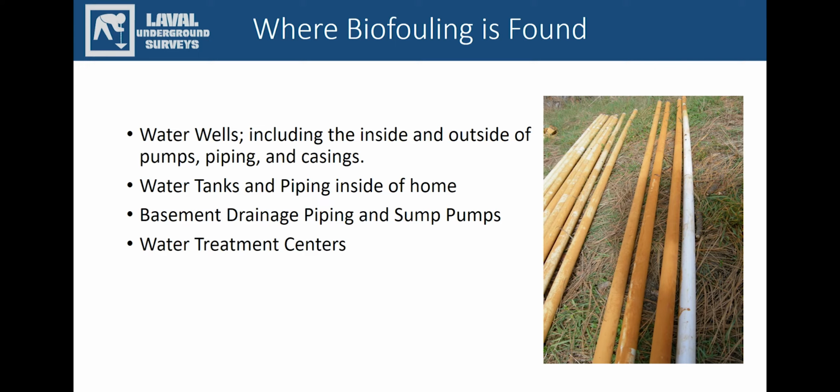Most recently, we've seen an uptick in the basement waterproofing industry looking for answers to iron bacteria problems. Because basements have water that flows into the drainage and sump pumps, the piping and the sump become clogged with iron bacteria. It's widely misunderstood in the basement waterproofing industry, and often people spend thousands upon thousands of dollars to remove the piping and the sump just to relieve the clogging. I consistently talk to homeowners who change their sump pump every single year because they're not informed as to how to even treat iron bacteria.